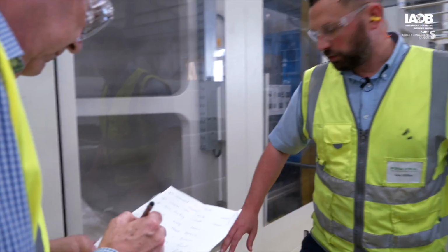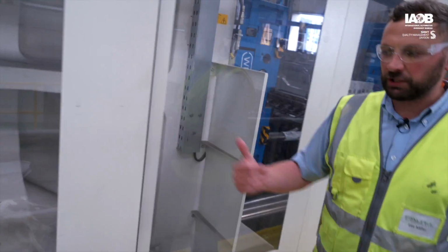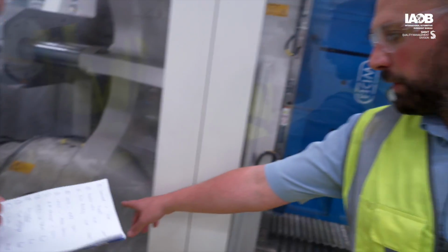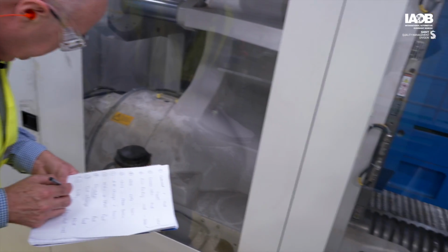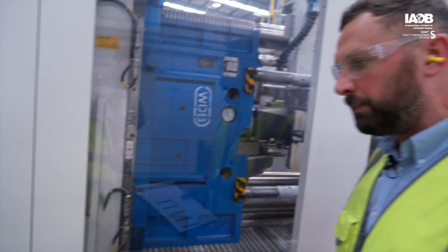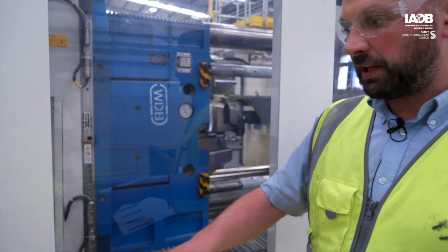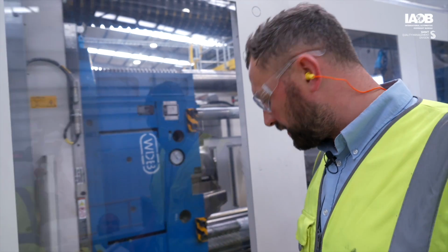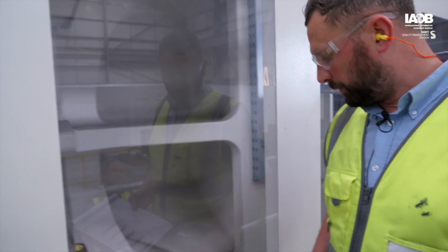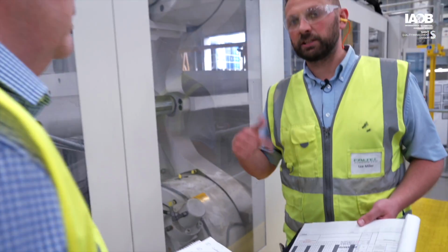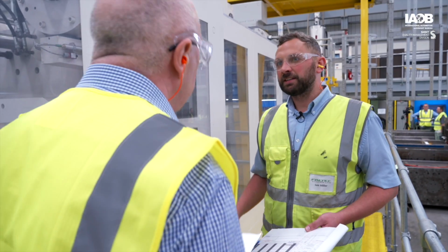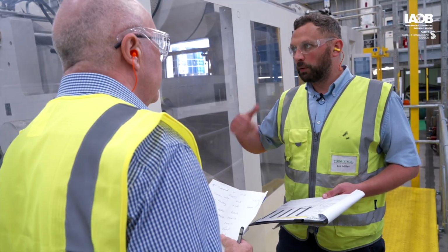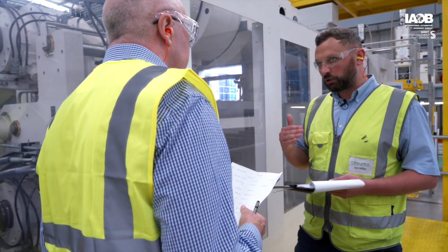Okay. So this will move. So this is the lubrication. It'll move because it's on the moving platen. So what we're checking here is this lubrication basically lubricates the slides, the mold where it opens and closes on. So we've got to make sure that that is full of lubrication oil. If that dries out, it'll be running on dry skids. So that one there is actually connected to the machine as well. And that's well above the minimum. Yes, so that's at medium level, so it's okay. We would keep an eye on that, it lasts quite a while. But we will be topping that up once it drops a bit more.